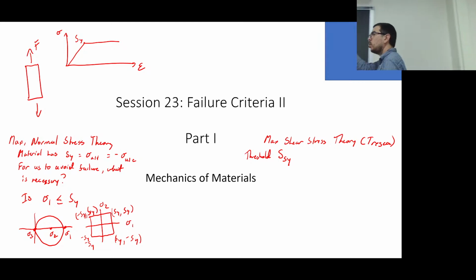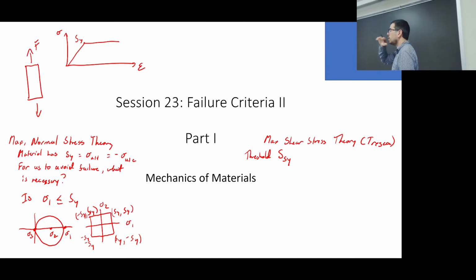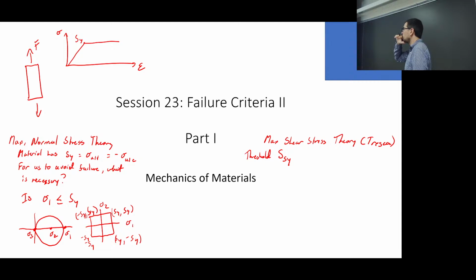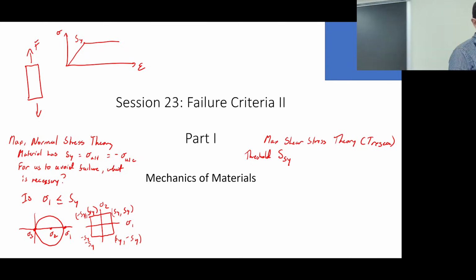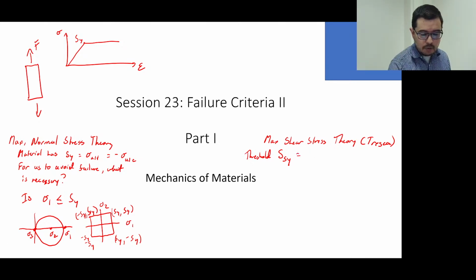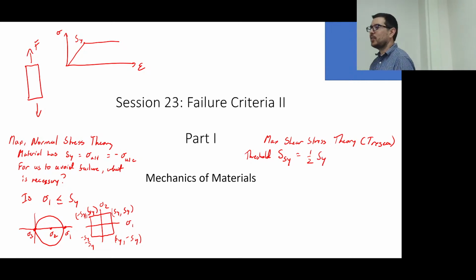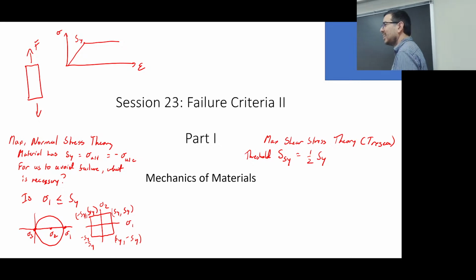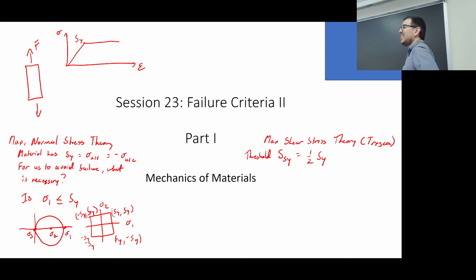Look, Javier. What is the threshold? Yes, the maximum shear stress. Okay, it's a maximum shear stress, but how do I calculate it? Yes, Andrew. It's the yield strength divided by 2. Yes, so it's 1/2 the yield strength. Now, how did you calculate that out? How did you know that, Andrew? I just remember it from watching the video, but I guess the Mohr's circle.